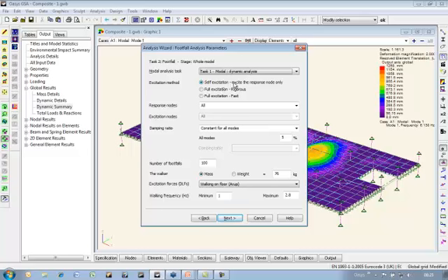Self-excitation usually finds the worst values, and what this does is apply the footfall excitation or dynamic loading function at each node, and then measure the response at that same node. Whereas full excitation, whether rigorous or fast, again excites each node but measures the response at all the other nodes, as we see here. And for the full detail, I should go for a fast analysis, fast full excitation.